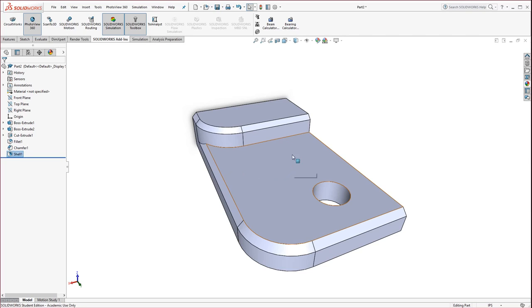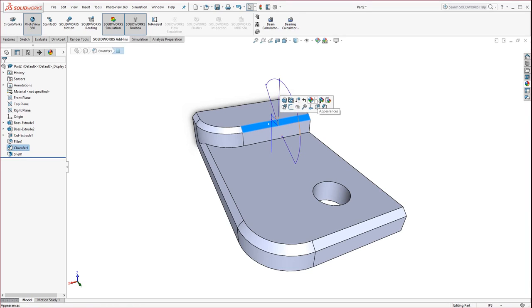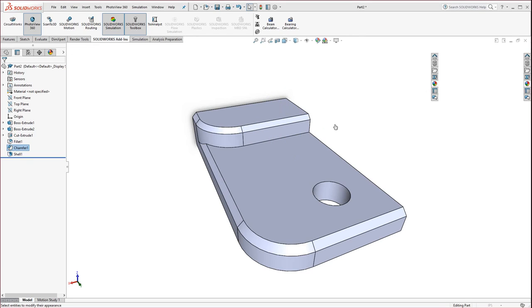Okay, now with that being said, let's say we wanted to just paint. Like you saw, I had blue edges for these faces here. You could select this face right here, and that's where these beach balls come in. You'll see appearances. If you hit the big beach ball, hit the little arrow to the right of it, you'll see you could change just that one individual face, the entire chamfer set or feature. So that's that one feature. If you look on the feature tree, chamfer includes both those chamfers. Or the entire body or the entire part file. We just want the chamfer 1, so go ahead and select that.